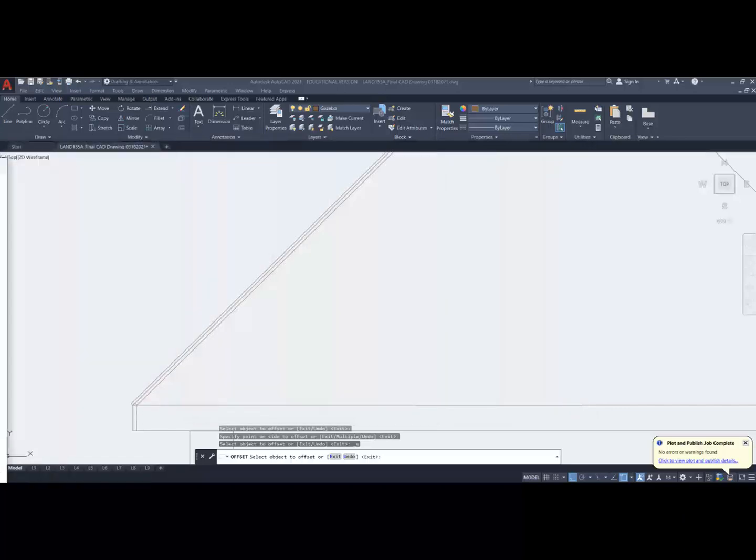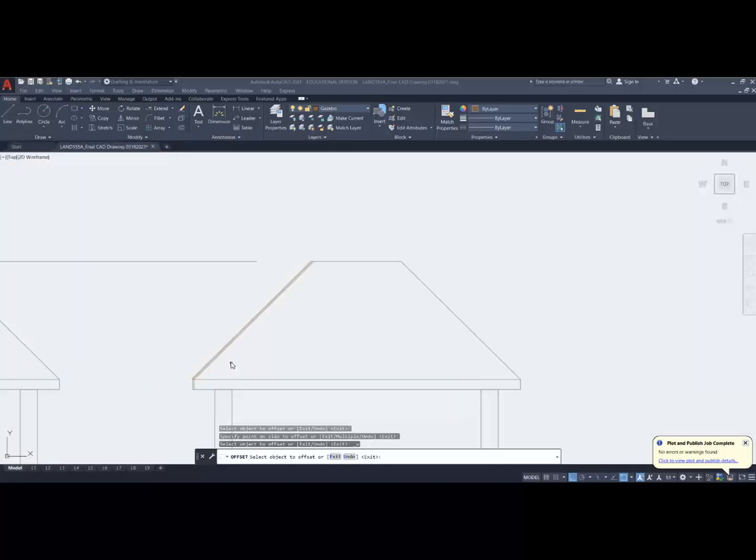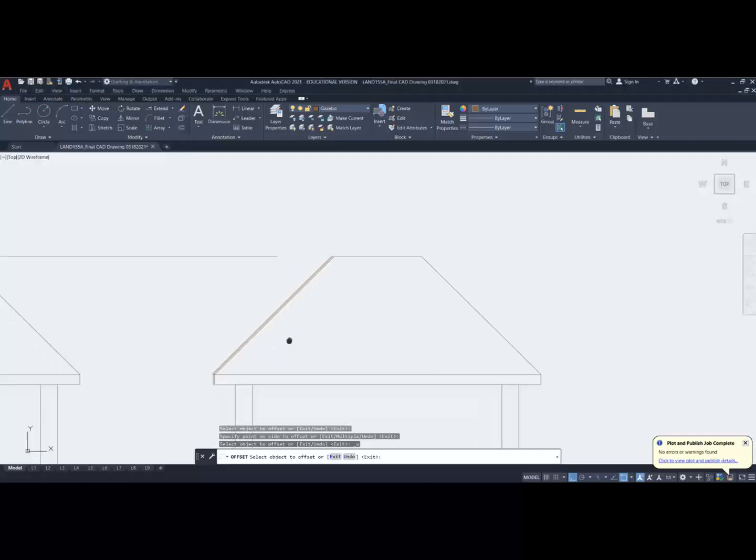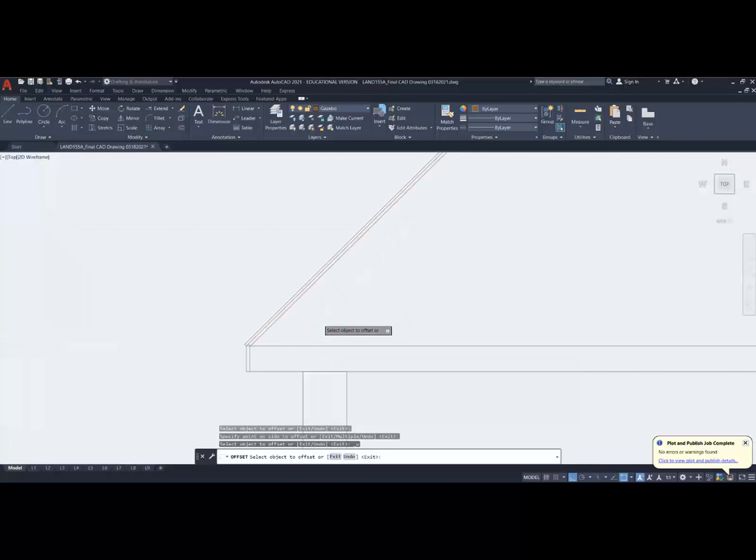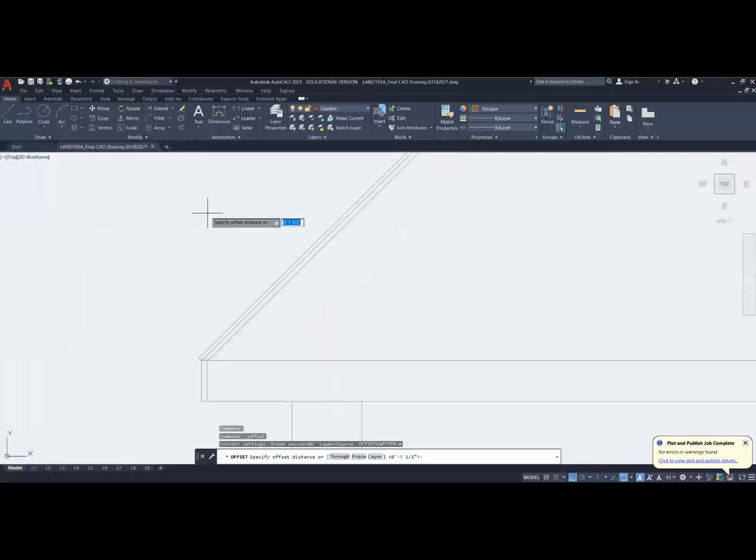And that's typically where in old construction roofs are damaged. So now I'm going to provide the ceiling joists. And the ceiling joists here I'm going to use 2x6s just because it's not a very large ceiling. And a 2x6 is 5.5 inches in thickness. So I'm going to offset this line 5.5 inches.